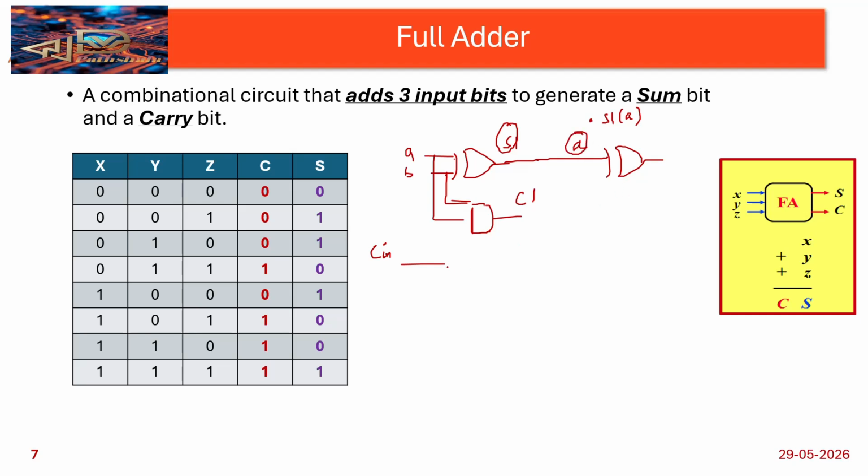And Cin is the other input, so that is the reason Cin is connected here. And then my sum output I am getting here, that is the original output, for the second half adder connected as .sum of sum. So sum is connected to sum, and the full adder circuit is working properly here.